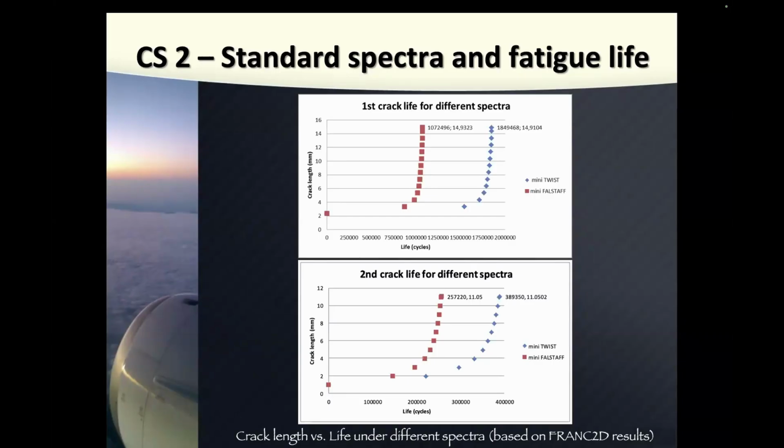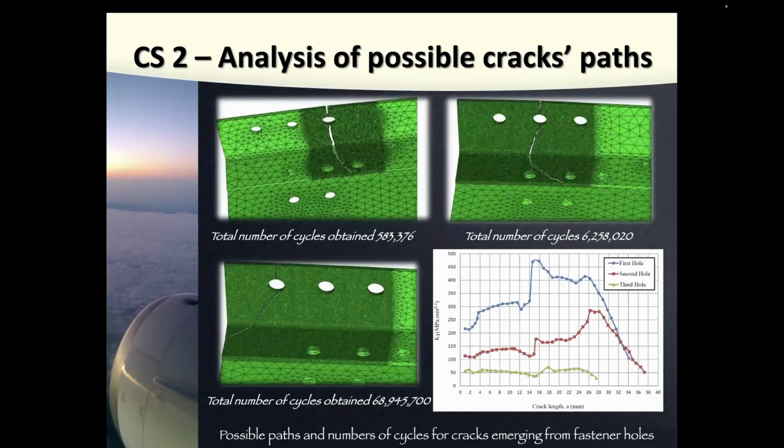There is always pressure from the airlines. Oh, can we postpone that for a week or 2 weeks? Because if they ground the aircraft, they lose money. You understand that? Because to fix something like this takes about 2 weeks. You have to disassemble the wing, take this part, break all these connections, put in a new part, then make the connections again. So it takes usually about 2 weeks. 2 weeks on the ground, a huge loss for airlines. So it's always a battle between designers and engineers, and the CEOs of the companies usually, because they just look at the numbers. They don't care about, unfortunately, okay, better not to say.